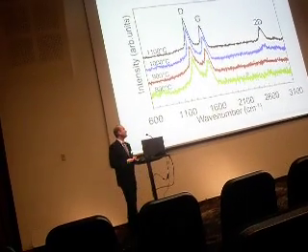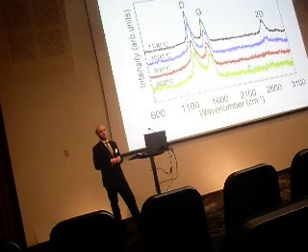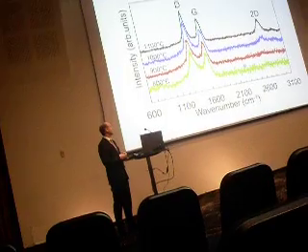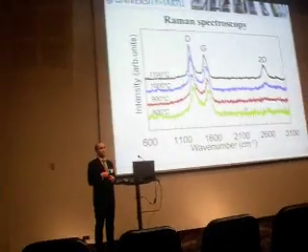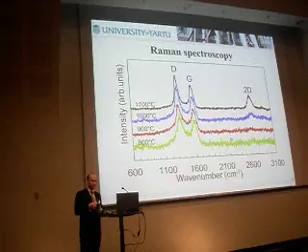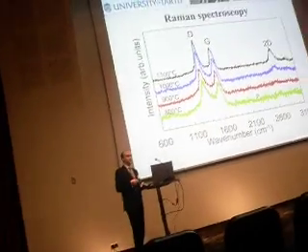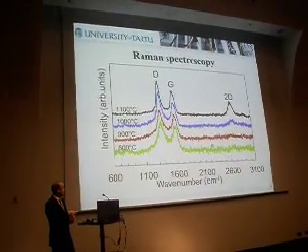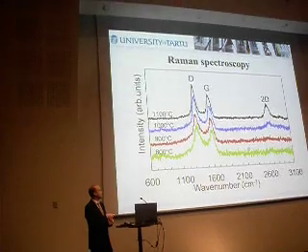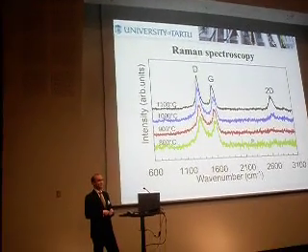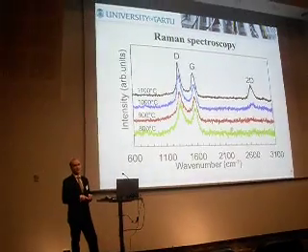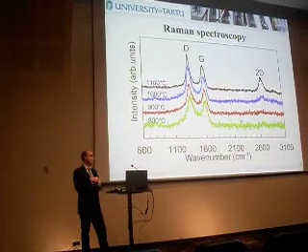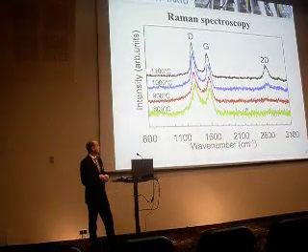And also we can come to the same conclusions when we look at the Raman spectrum of the material. But also what we can see from Raman spectroscopy that we couldn't see from the X-ray diffractograms is that at higher synthesis temperatures, the 2D peak, which comes out only in graphitic materials where the graphene layers are stacked together, starts to emerge.